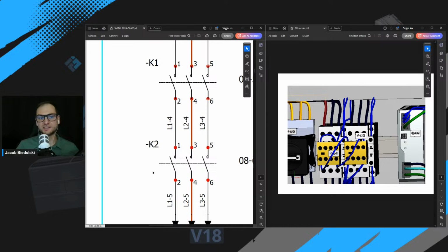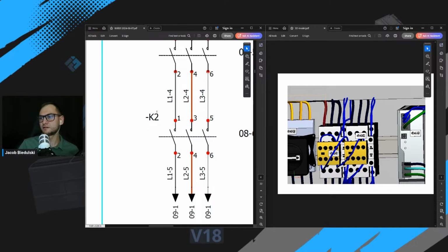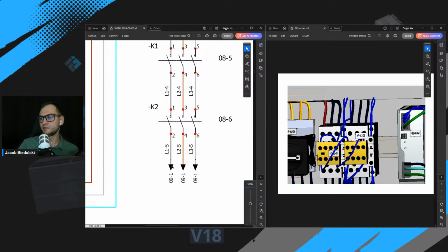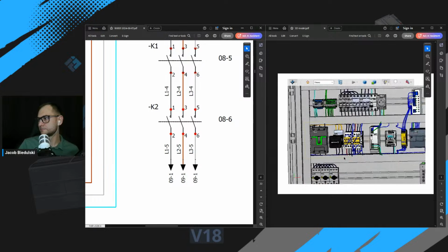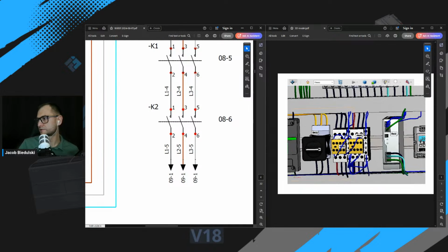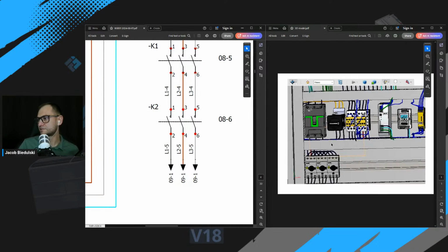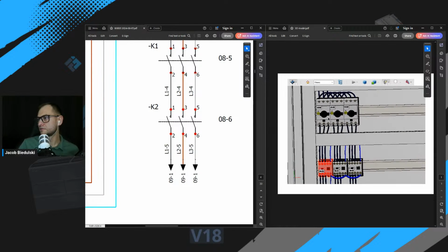If the safety system is up and running, is reset, and everything works fine, those contactors conduct power to the section with motor circuit breakers and contactors for the DOL starting system for induction motors.